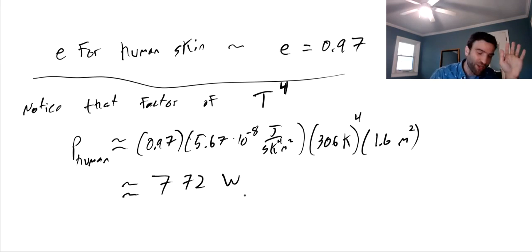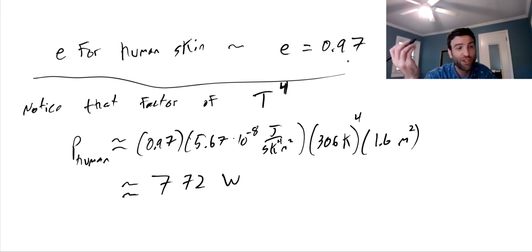As long as the coat is a poor conductor, which is to say a good insulator, right? Another thing that we can do is play around with the emissivity. So if we're just standing with just human skin, the emissivity is pretty high. But what if we wrapped ourselves in something that had low emissivity, like shiny metallic clothing, where the emissivity can be a lot lower, right?